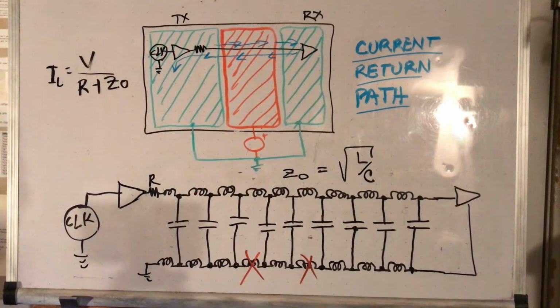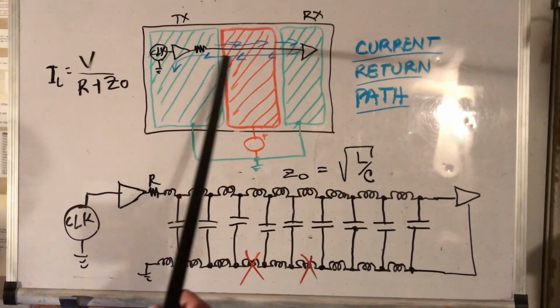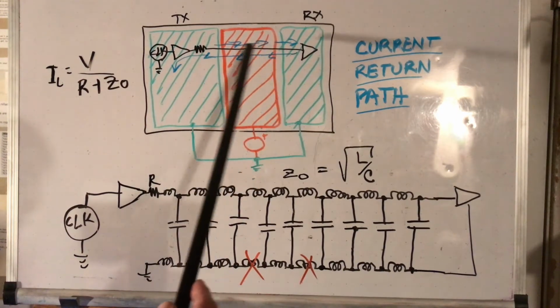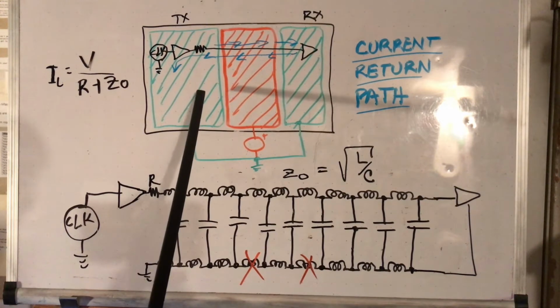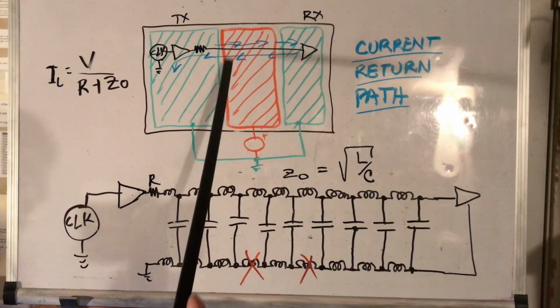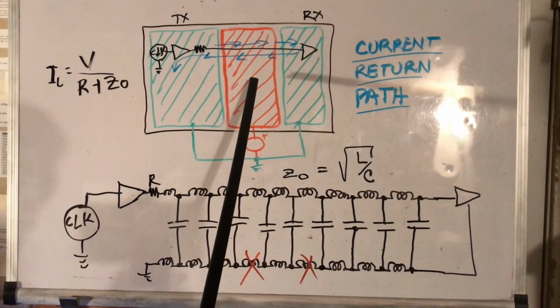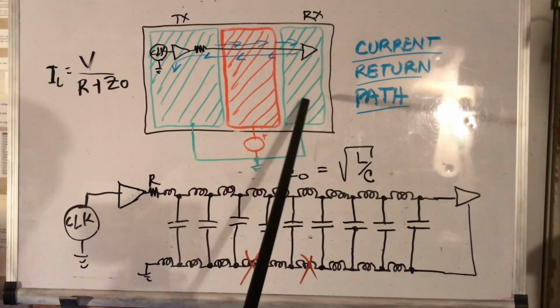One problem that is often faced by PCB layout engineers is that they are required to move fast signals across large boards, where the signal starts at a reference plane that is properly at ground level, then crosses a moat, goes into a region that is referenced to power, and then goes back to being referenced to ground, to another plane.